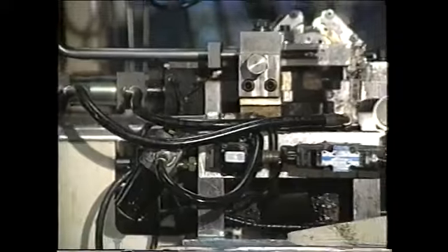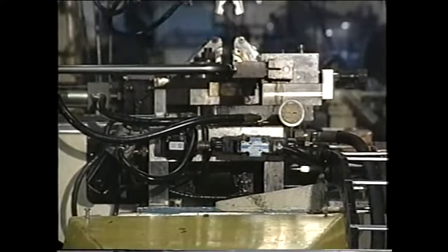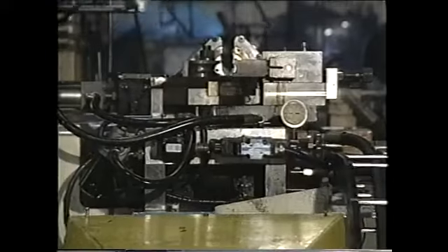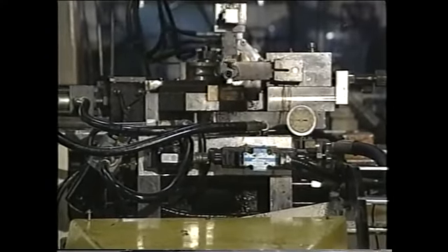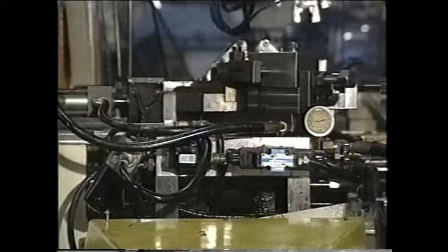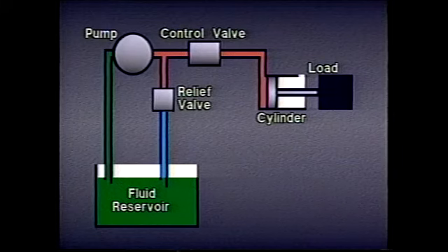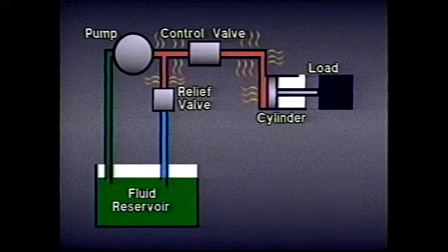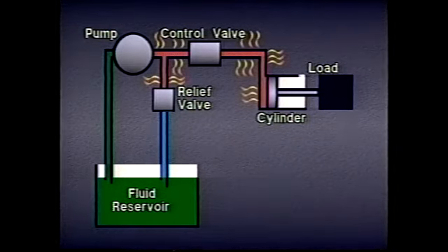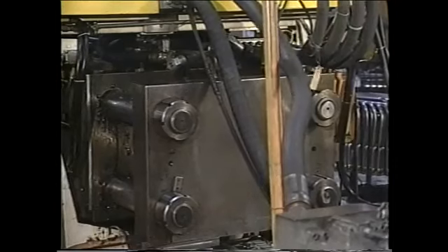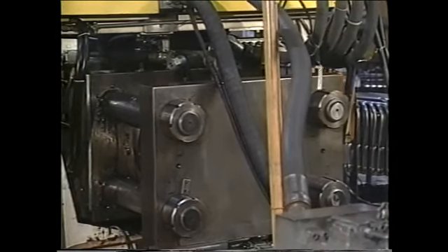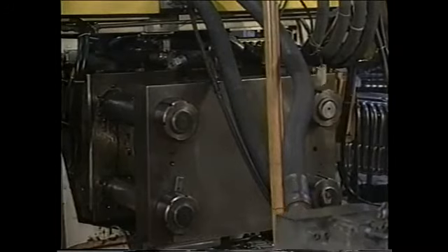In a hydraulic system, energy in the form of a pressurized liquid is transmitted through piping or tubing to the point of work. The working energy of the pressurized liquid is converted to mechanical energy through the use of various types of actuators. However, not all of the working energy in our hydraulic system ends up producing useful work. As the pressurized fluid moves through the hoses, some of its working energy is converted to heat energy because of friction.